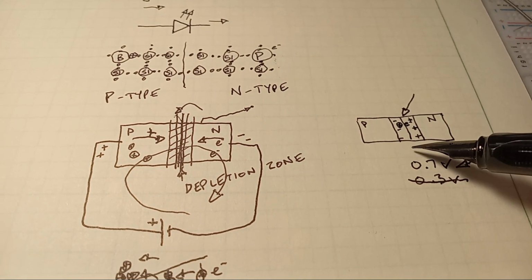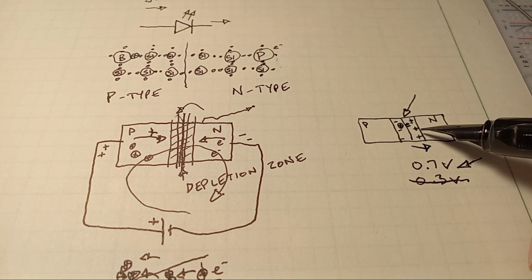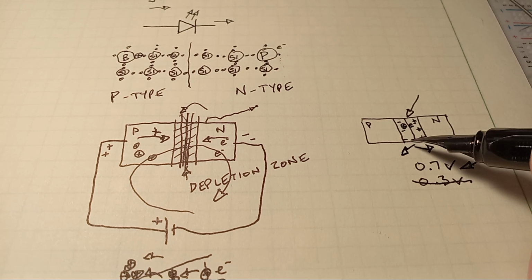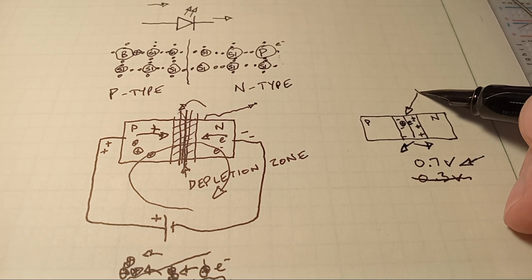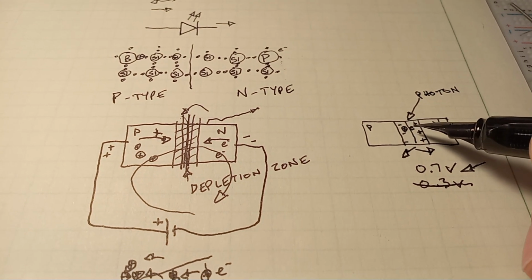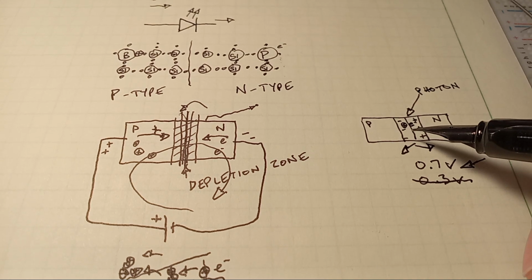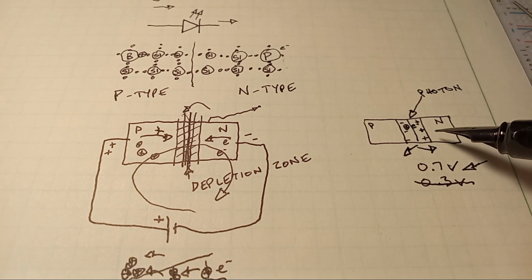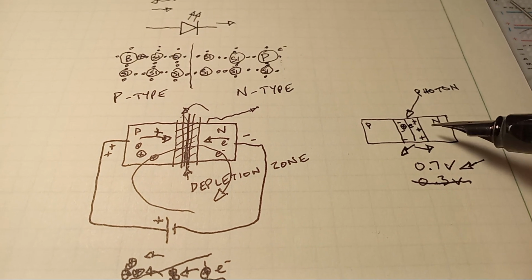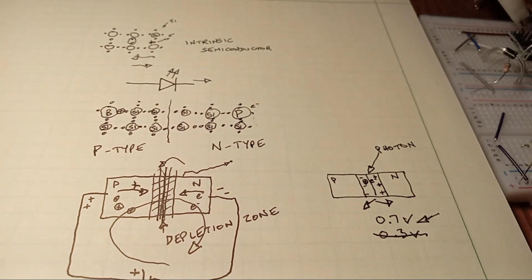But because the electron is negatively charged, it gets pulled over here to the positive, and the hole is likewise pulled over here. So what this means is that if you add a photon and it smacks an electron out of place, the space charge region tends to pull the resultant hole and electron to opposite sides of the p-n junction, which means you can use one of these to convert light into electricity. This principle has found wide application nowadays.